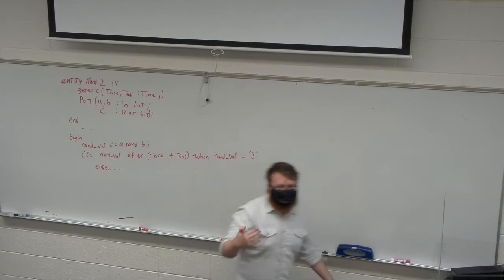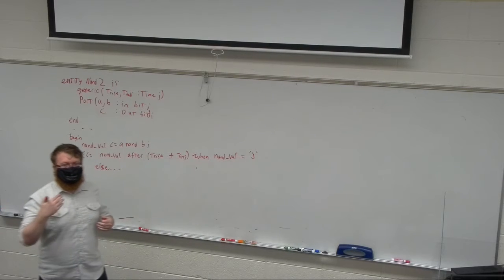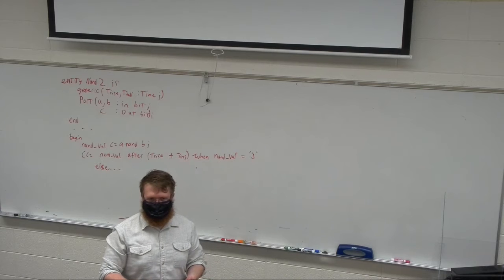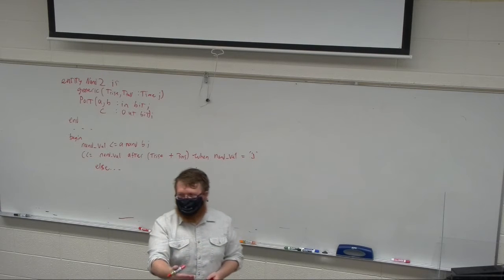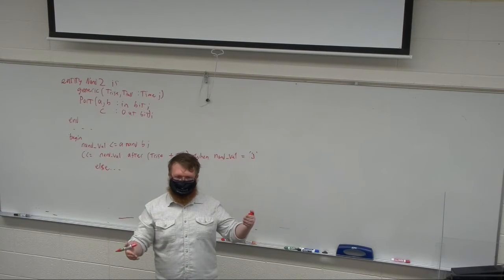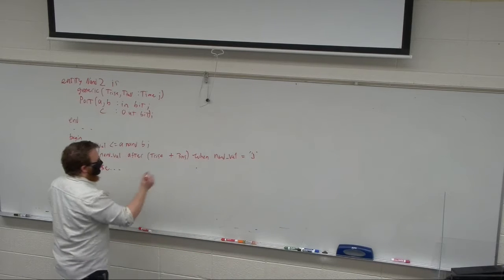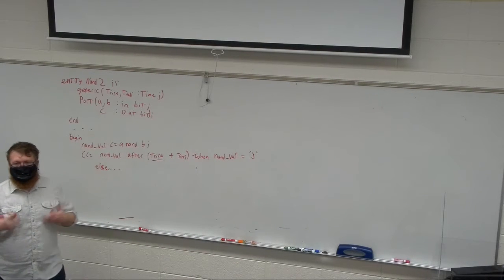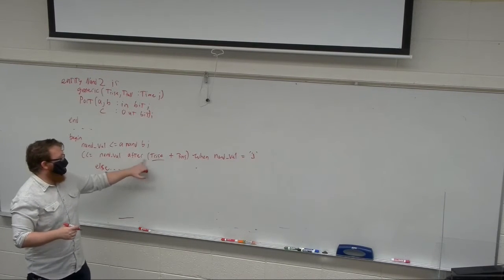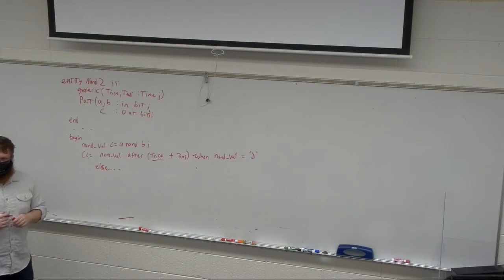So, in this case, let's say I was building a NAND gate, but its rise and fall times changed based on the number of devices that I was attaching it to, right? Because a gate can only drive so much capacitance and meet timing. So if I connect 100 devices to the output of this one NAND gate, it's going to slow down. So in order to simulate correctly, I'm going to say that it has a rise time that changes based on the number of devices. Now we know that this after doesn't synthesize, but we want to simulate things correctly.